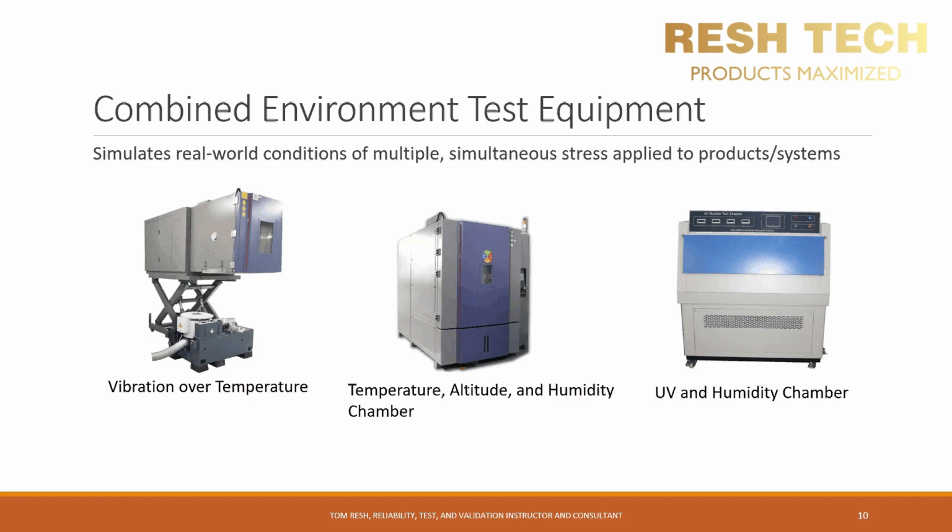Temperature, altitude, and humidity chambers is another type of combined environment system. Temperature, altitude, and humidity testing has real-world applications and is also called out as a test in the 810 MIL standards. These tests can get really tricky, and I can dedicate a separate video on altitude, temperature, humidity testing if you are interested. So comment below and I will make it so.